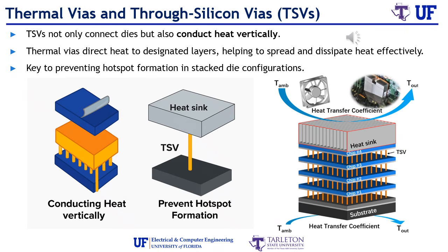Thermal vias and TSVs act like tiny metal chimneys, giving heat low resistance pathways from interior regions to surfaces where heat spreaders and sinks can work. Their effectiveness depends on geometry, diameter, length, aspect ratio, as well as spacing and fill material. Too few thermal vias leave hot regions isolated. Too many consume area, complicate routing, and may affect mechanical integrity. In practice, designers combine signal TSVs with dedicated thermal vias, concentrating extra thermal paths near high power regions.